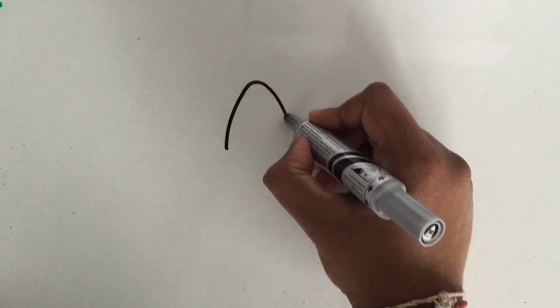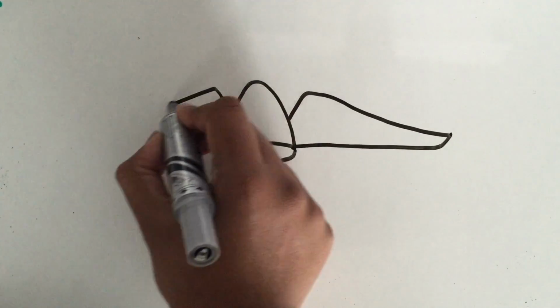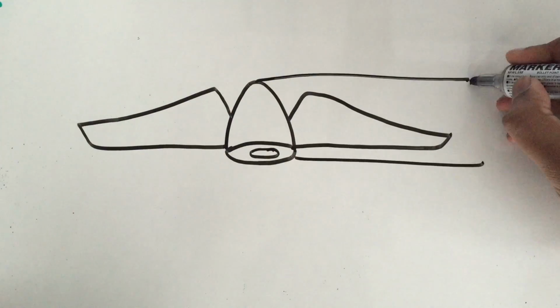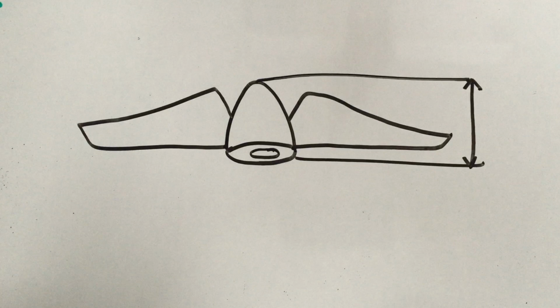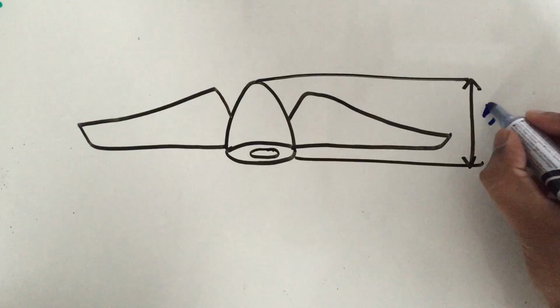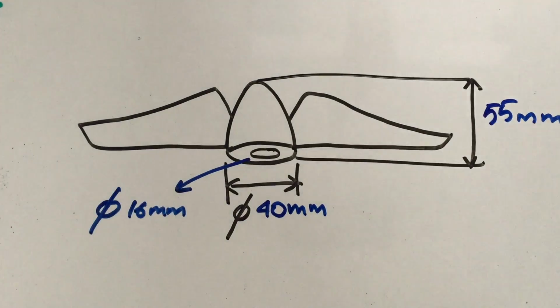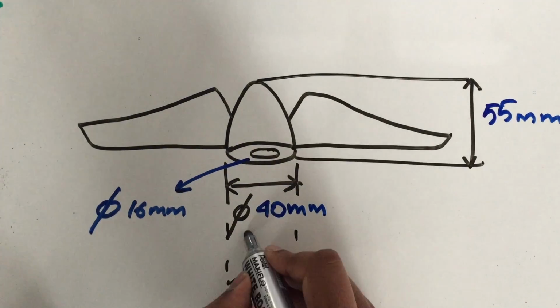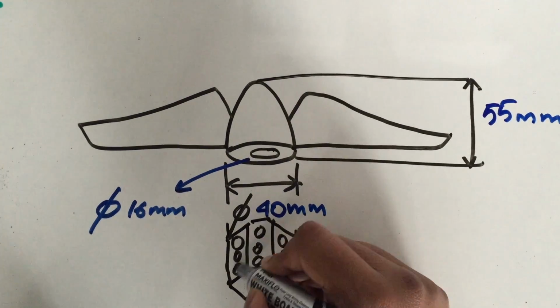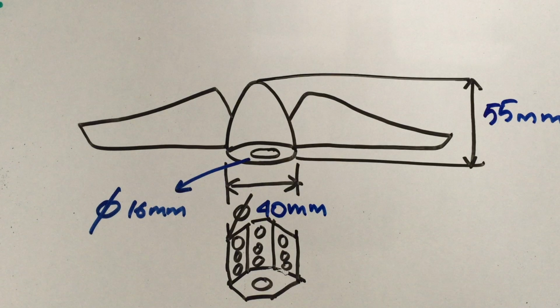The part joining the 2 turbine blades, called the hub, also requires some design considerations. We determined that this element of the design wasn't likely to impact performance greatly, and so we opted to keep it as simple as possible, choosing a depth of 55mm and a diameter of 40mm, in order to accommodate a 16mm diameter mounting shaft securely. In order to minimize weight, we decided to drill holes through the aluminium component joining the blade structure to the shaft.